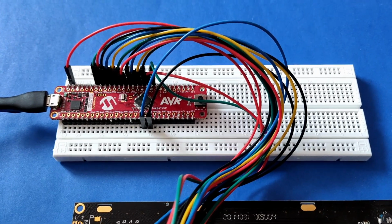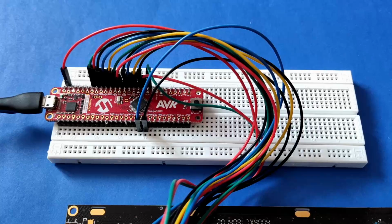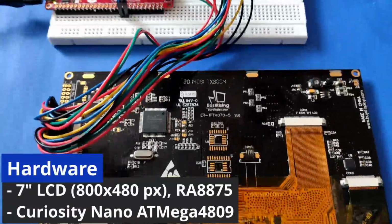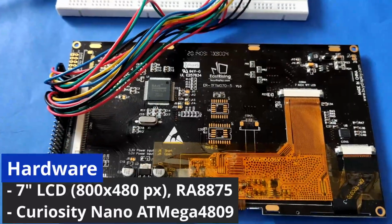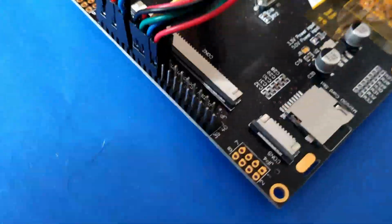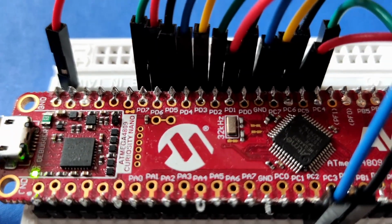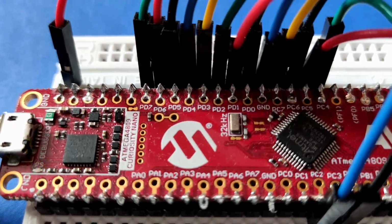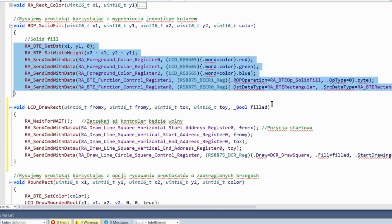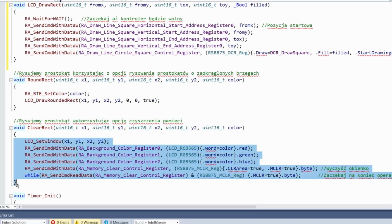To measure the execution time of the mentioned functions, I assembled a test hardware, as you can see in the film. So here is my test hardware, which consists of a 7-inch display, 800 by 480 pixels, controlled by the RA8875. The LCD controller is connected to an Atmega 4809 using an 8-bit parallel bus. Actually, the bus type is not important. You can use a serial bus as well, because all I have to do is send a couple of bytes to the RA8875, which are the actual commands.